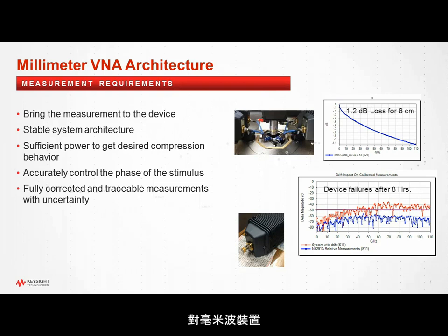The impact of this is very heavily seen if you're looking at these millimeter wave devices and trying to do maybe an on-wafer measurement. You have like 3,000 parts on a wafer, depending on the size, and you start a run that maybe lasts 16 hours or 24 hours, and after 8 hours you lost about 50% of the parts because you've basically failed good parts in that case.